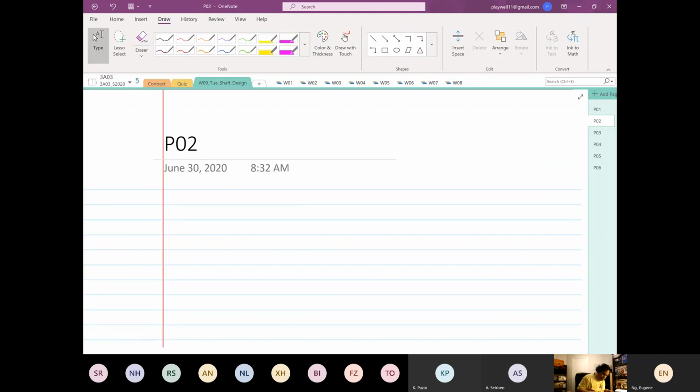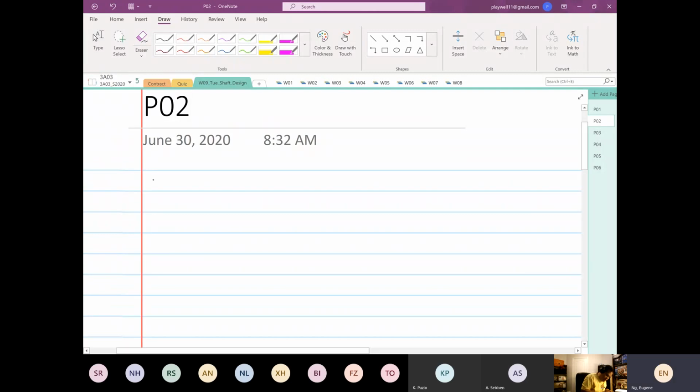So what you see is tau max will be equal to sigma M over 2, which is My over 2I, because stress M is divided by 2, plus the shear, which is Tc over J. So now you see the relationship with moment and the torque.